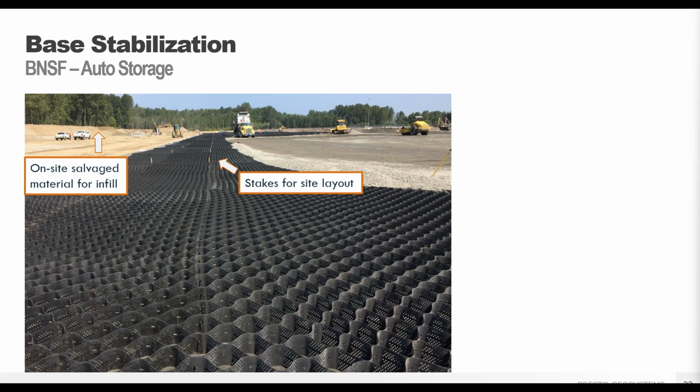At the far left, we see where the contractor stockpiled the on-site sandy soils to mix with crushed aggregate and save construction costs. The expanded and connected GeoWeb mid-screen, and the filling, then compacting as we move to the right. Again, this work in parallel across the site allows for an even more efficient installation process. Here we also see the stakes for the site layout from the site survey. These technique tips made for a very efficient install for such a large project.